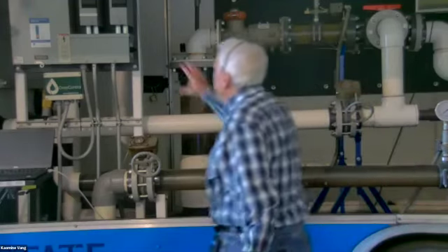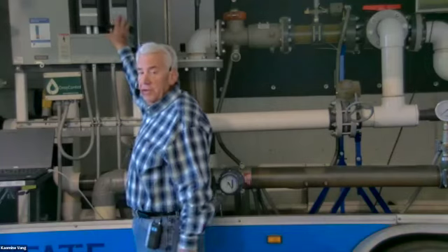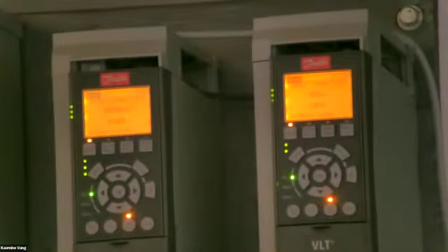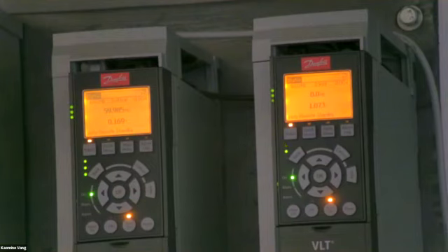And then finally, we get back again to our 2 VFDs here on the close-up. And one's for each pump, and you can see it shows the hertz that's going to run there. You can't really see it very well. Oh, let's see on the screen there. I ran this one already. This one pump is ready to go right now. It says 59.985. It's basically 60 hertz. It's full speed when I'm running that pump. I haven't run the other pump, so it doesn't show anything today as far as the VFD goes.